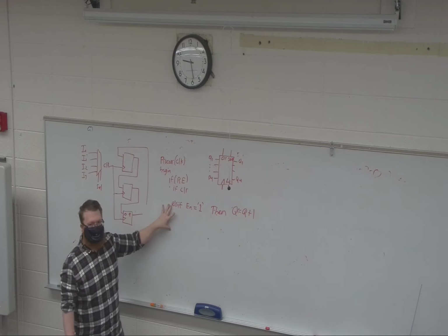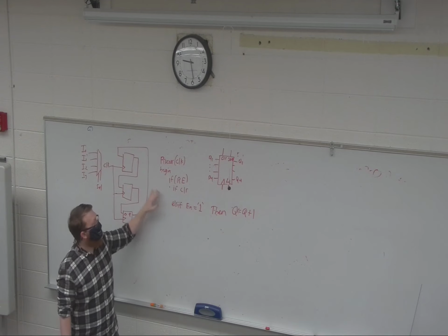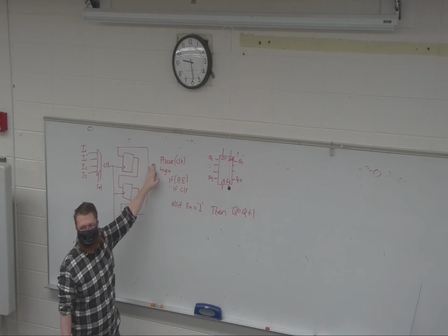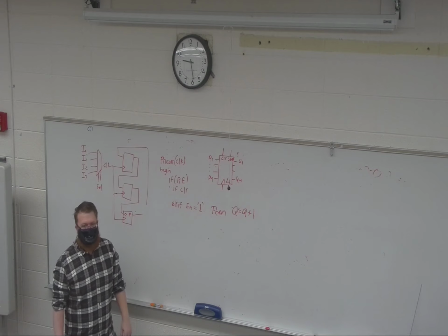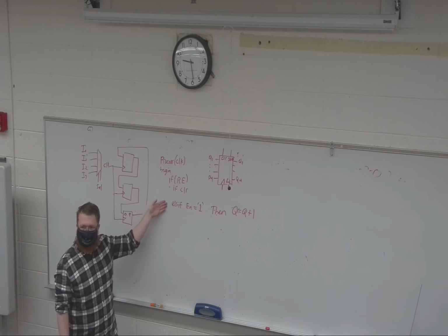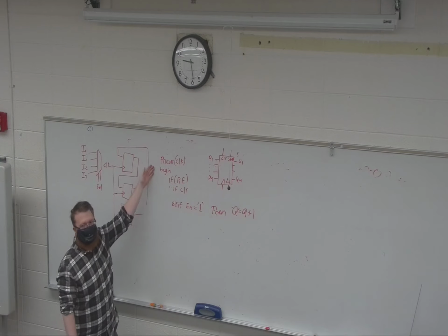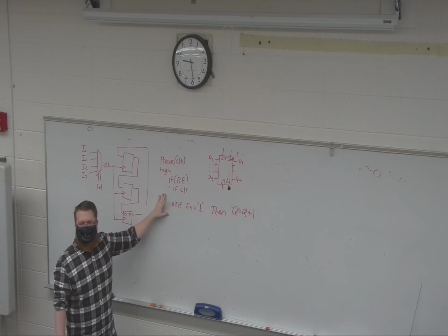I'm not going to dive into it right now. We'll probably get into that later of why that's true. But if you just count on every clock, you can end up with an issue, it really comes down to a timing issue. And so you may want to count every time some event happens. That event might be happening at 10 kilohertz, and your clock is 100 megahertz. When you do that, run the process at 100 megahertz, and then put the enable signal on whatever event you're trying to count.